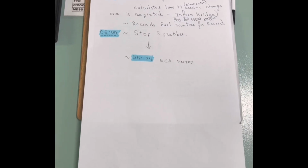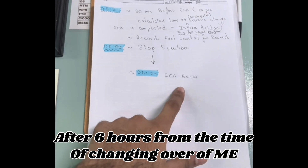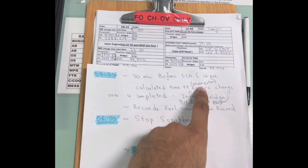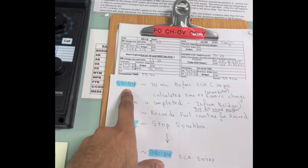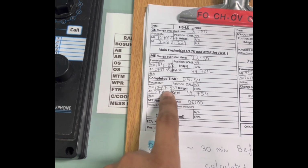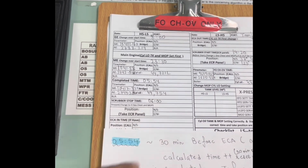So good morning guys. So I was informed that around morning 0624 will be the ECA entry. So as per the calculation, we are already in low sulfur. We have also given a 30-minute extra reserve time. So 0554 is the complete changeover time. I have already recorded the fuel counters for the main engine, auxiliary engine, and for the cylinder oil counters.